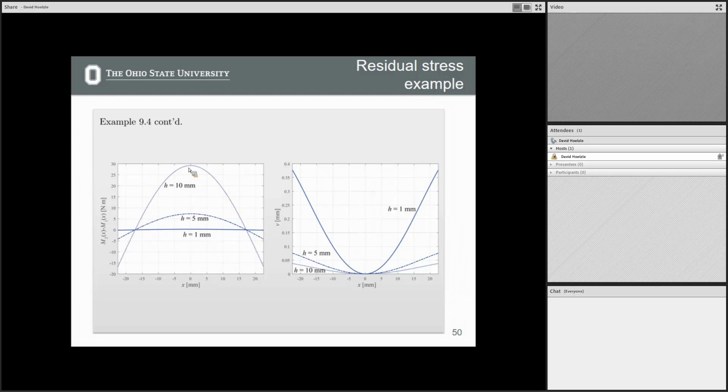But you get somewhere maximum around 30 Newton meters, which is a lot. So stress levels, this is considerably high stress levels. I calculated that when I was working through this problem, somewhere around the range of 200 megapascals. So it's a lot of stress in the part. But it's thick. It's a pretty big chunk of stainless steel, right? So it actually has the ability to resist that quite well.